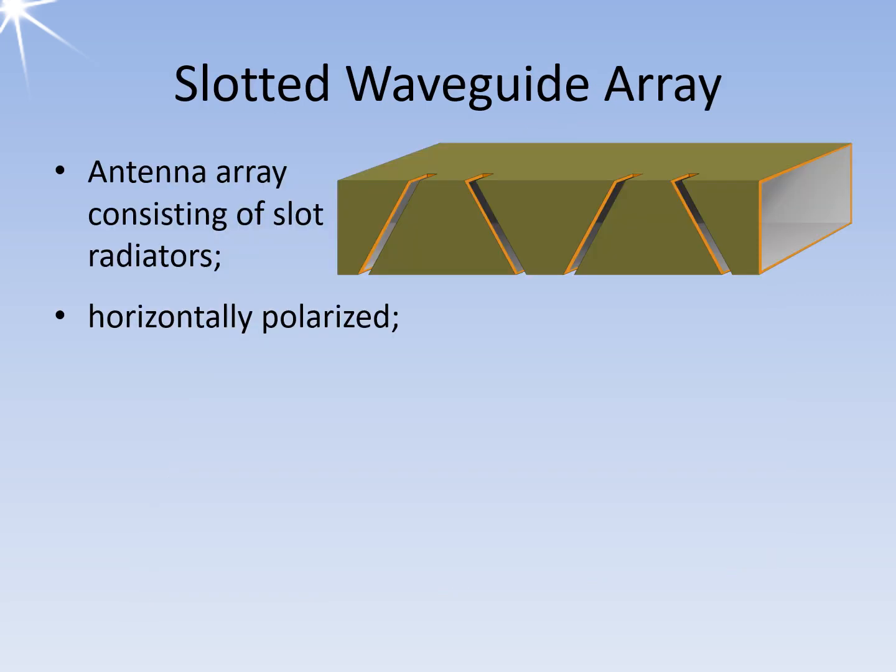Slot radiators are essentially gaps or openings in an electrically conductive surface that can be considered infinite. As per Babinet's theorem, they are equivalent to a half-wave dipole in their function. Unlike a vertically aligned dipole with vertical polarization, vertical slot antennas provide horizontal polarization.